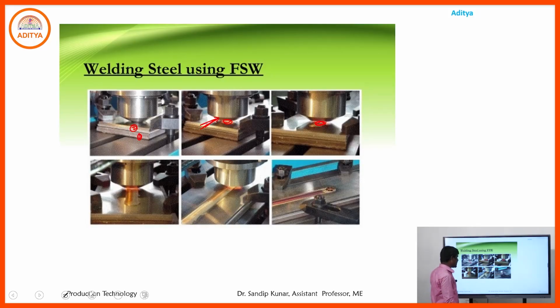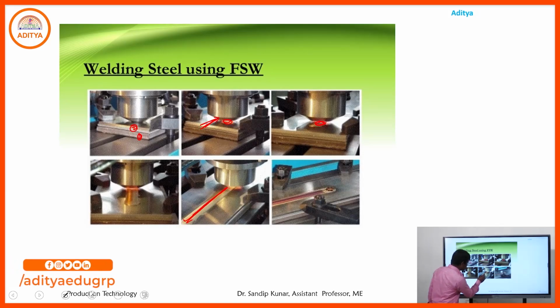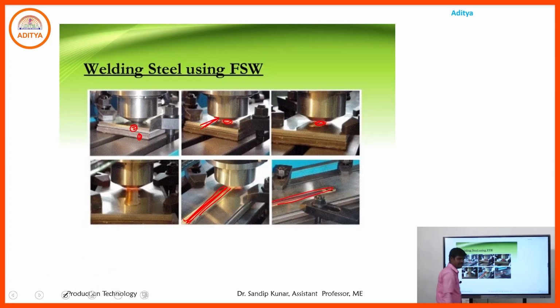Due to that, the welding takes place across this zone. That is the welding surface. Between the contact surface of the probe and the welding faces, what happens? Heat will be generated due to mechanical friction.